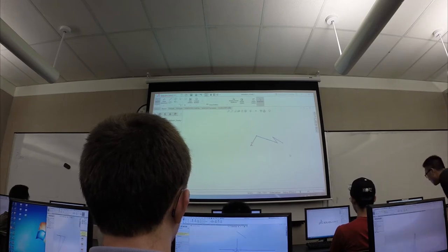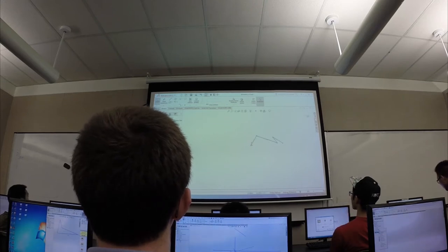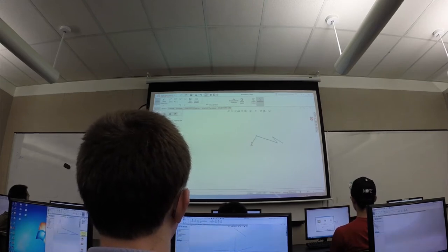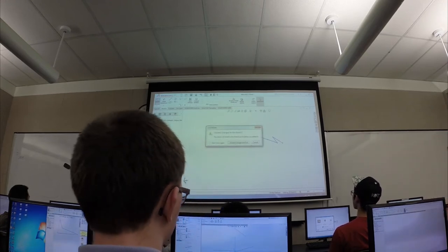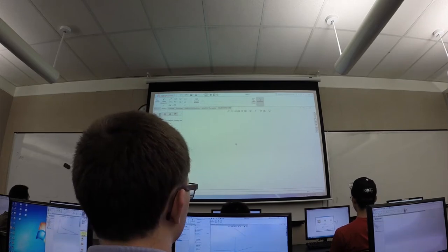So if you made a 3D sketch, just right-click here in the feature tree. You see that it has 3D sketch, right? Right-click on it, and then just, oh, we can just delete it here. Never mind. There's a little X sign up on the top right corner. Just click it, and then it'll cancel out any other changes we made. Cancel changes and exit. Cool. So we're back to the start.